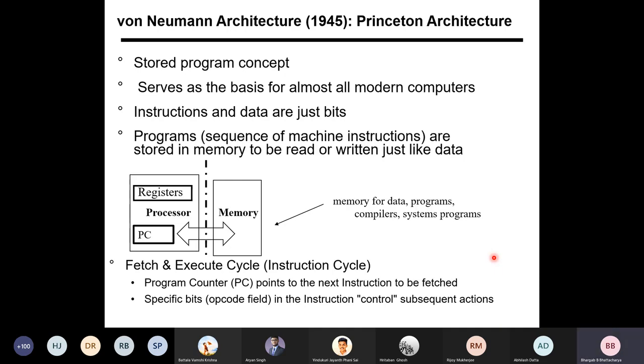And these codes will tell you what sort of instruction it is, whether it is an add instruction or a logical AND operation, or a shift instruction, or a branch or if then else. Depending on your instruction set, you encode each instruction by a distinct opcode, and that opcode would occupy certain specific bits in your instruction, which may be assumed to be 32 bits.